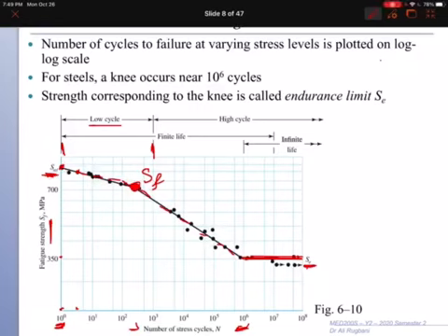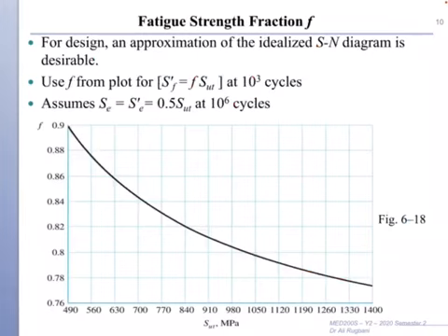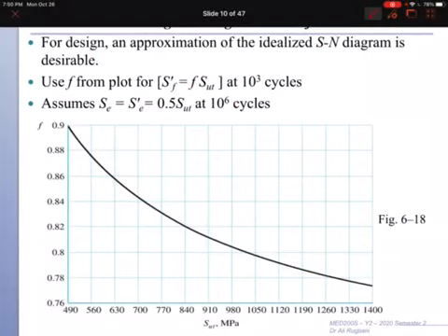Now we know the value of endurance limit, and remember this value is the ideal value until now, and that is a factor of ultimate strength. So the value of strength of failure at 1000 cycles will also be a factor or a percentage of ultimate strength. So this curve links the value from ultimate strength with the value of strength of failure at 1000 cycles. This will give you the missing point.